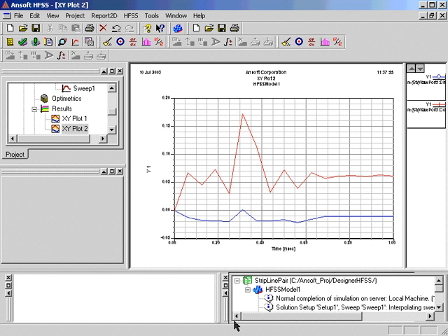Due to the narrow frequency range of the simulation, we have minimal resolution in the TDR plot. However, the discontinuity in the common mode signal is clearly visible and is clearly minimized in the differential plot. A detailed discussion on TDR is beyond the scope of this tutorial. However, the process for creating TDR data is consistent for more complex structures with wider bandwidth simulations. For now, we'll close the TDR plot and move to the topic of exporting the solution data to a SPICE model for further time domain simulation.